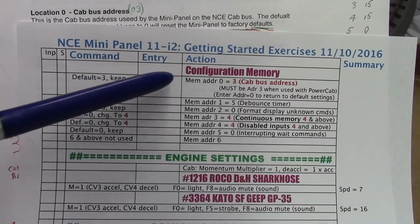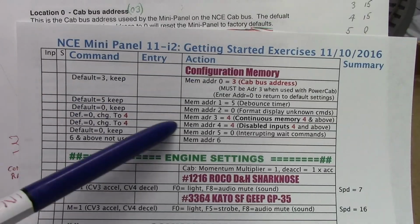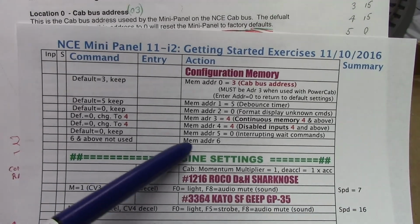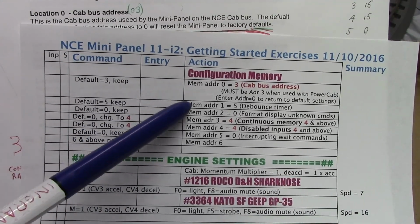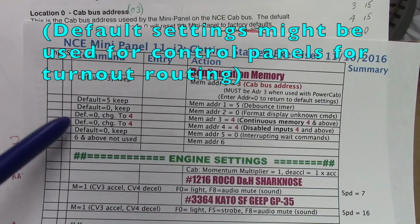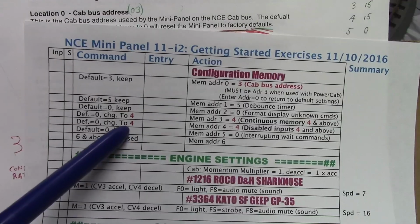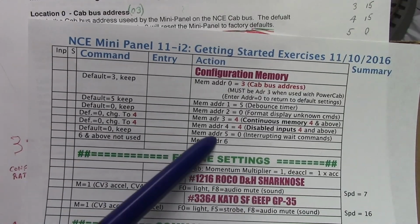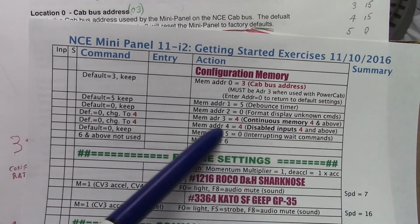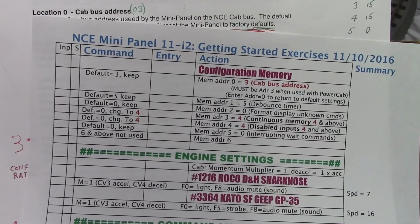Here's the programming sheet for the original video 816 getting started, and these are our configuration memory addresses 1 through 6, and we use the default for memory address 0, 1, and 2. Memory address 3, which is continuous memory, we change that to 4, the default being 0. Memory address 4, which is the disabled inputs, the default is 0, we change that to 4. And then the rest of the stuff we let alone. I don't think these upper memory locations are even used. The important ones are 3 and 4, and 0 if you're changing the cab address, which you probably won't need to for a while.